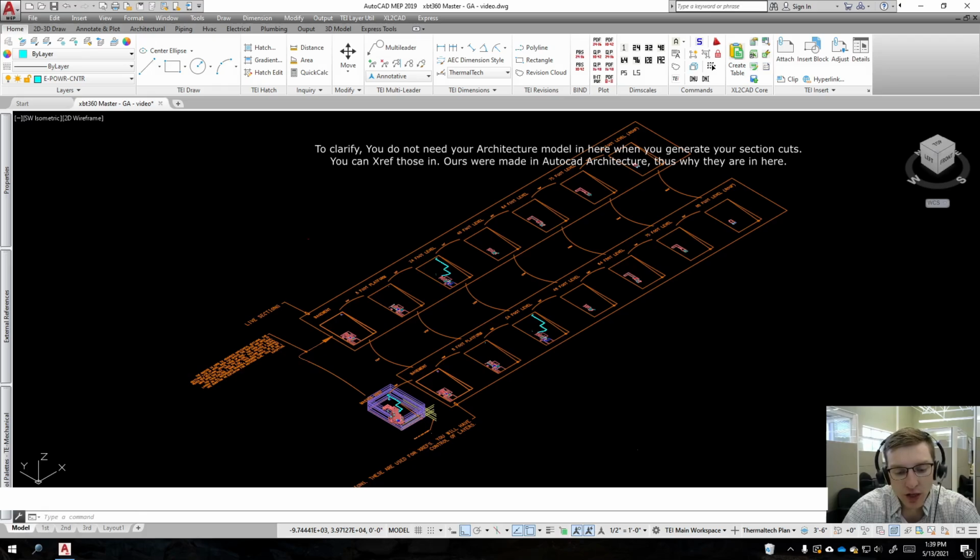If you were given a chiller from a manufacturer and you put it up on the second story of your building, and you do a global cut plane to cut your piping and all that jazz, everything's going to look fine except that chiller will not be affected by the global cut plane at all. Or let's say you have a piece of equipment that is 50 feet high. If you try to cut it using global cut planes, it's just not going to work.